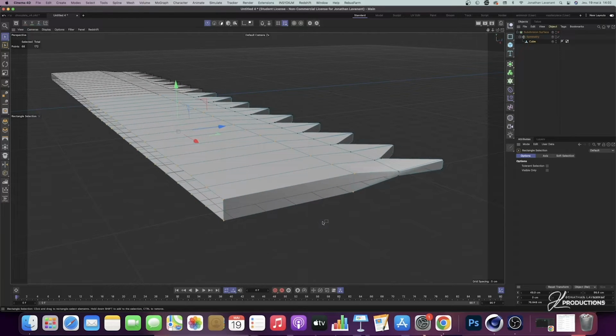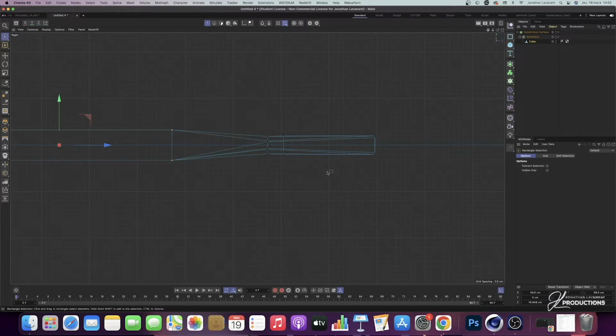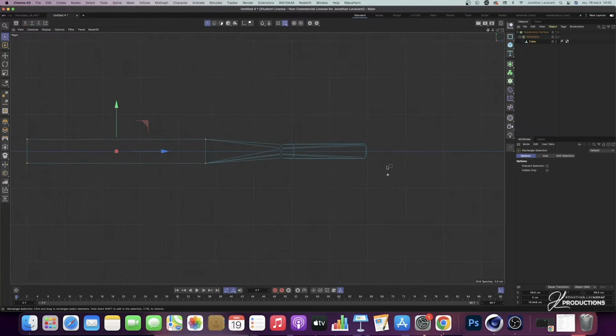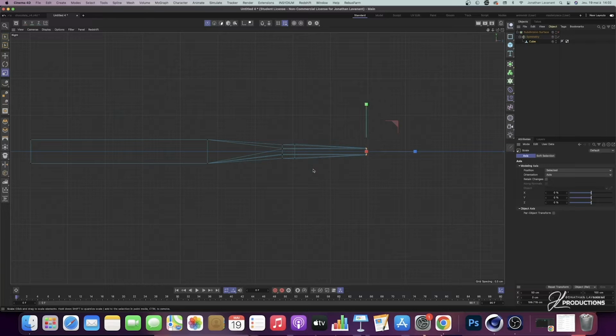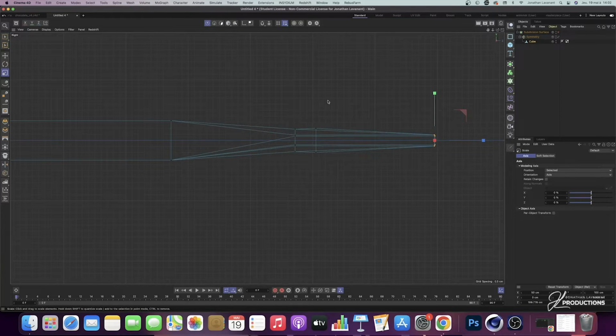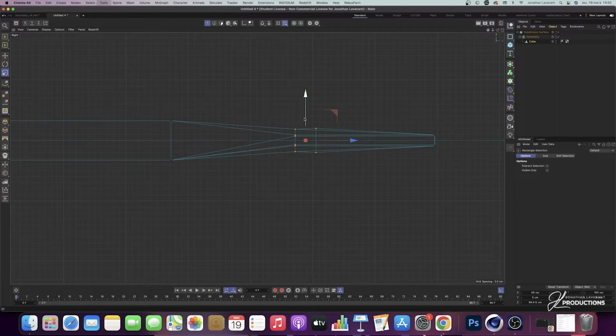So then put yourself back inside view, and I'll be able to adjust the size because there, it may be a little too thick. So there I will select the points here. I press T, I just reduce them roughly like this. I just select the points that are linked, the points that are right here. I press T and I'm going to do the same at this level.